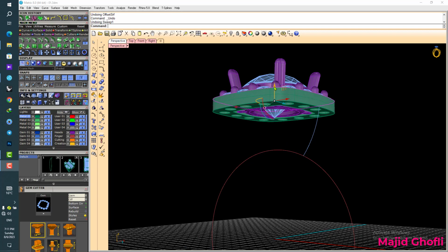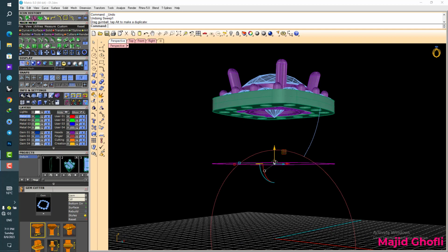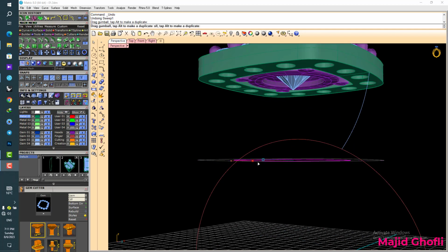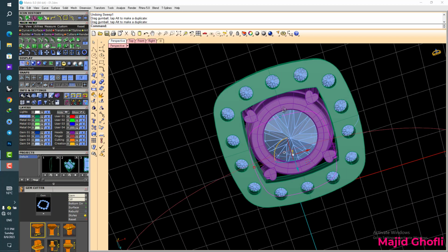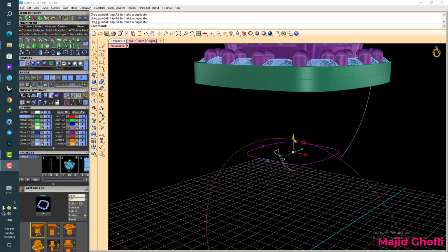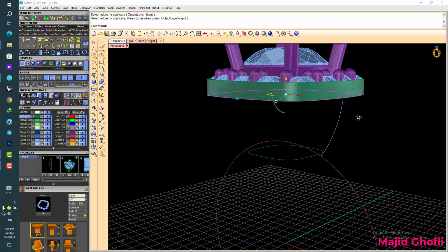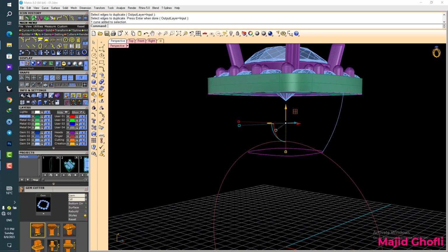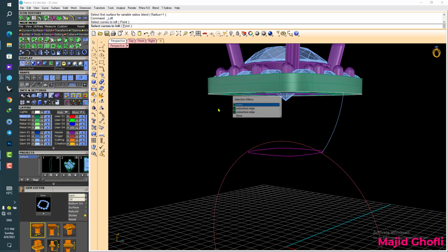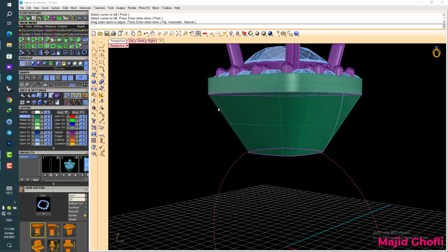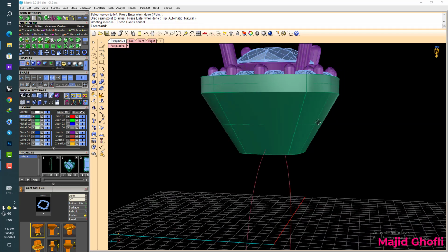for the second command, we can reach our desired shape by using two lines, yes, at the top and at the bottom, using the Loft command. Okay, so go to the curve and yes, duplicate edge and select both curves and go to the surface and use Loft. Now look at this.